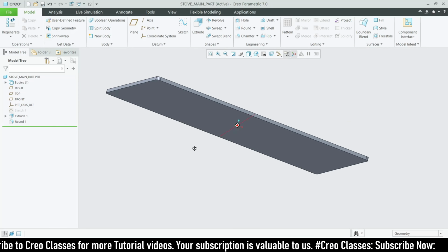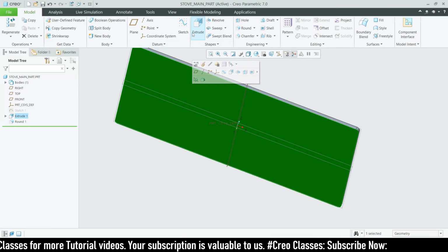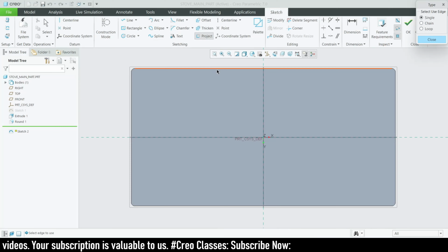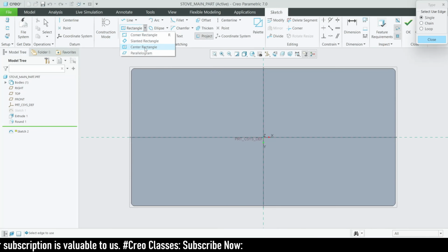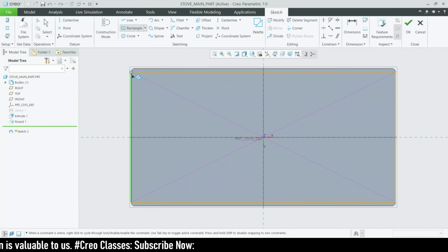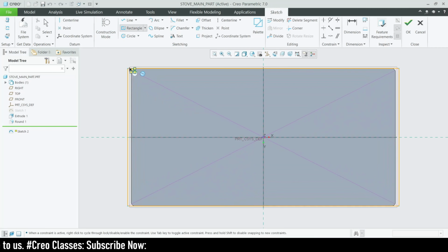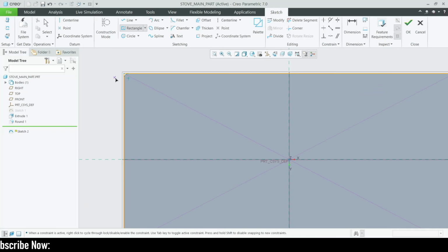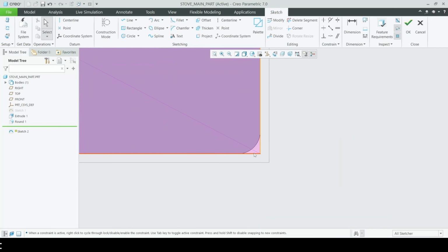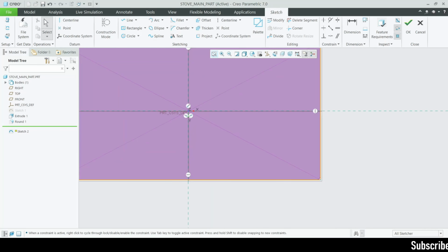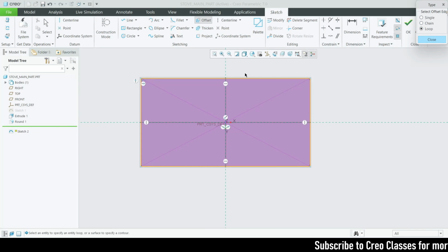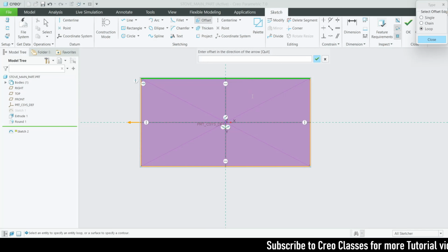On the back side, I'm going to sketch on the back face. Let's go for the sketch and the sketch view. Before that, I want to draw a center rectangle up to this height and this distance value. It coincides with this line. Then I want to offset the loop, offsetting all of this by minus 10 towards the inside.